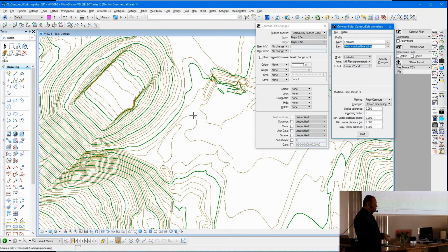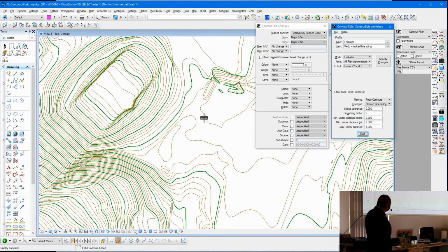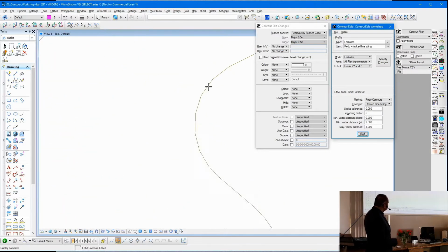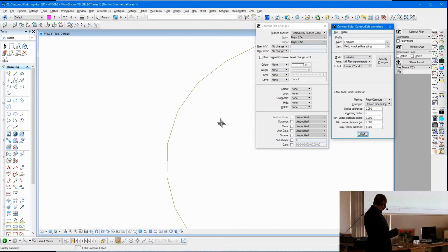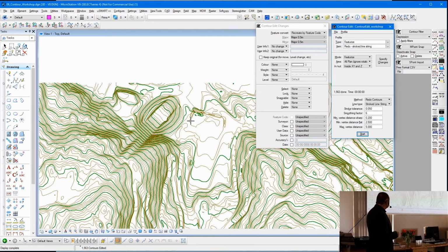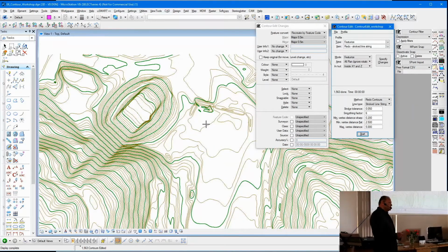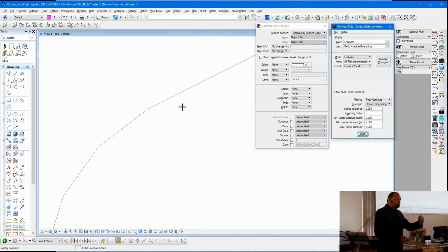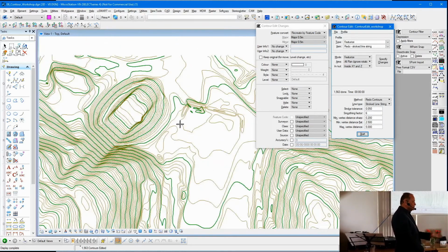And now we're going to refeaturize them as line strings at a particular tolerance, where we specify how much the line is allowed to deviate from the curve. Okay, and that's over here. Where's the tolerance? So we know that there won't be more than a 5 centimeter deviation from the contour. And we've got something that, zoomed out, looks like curves, but close up you'll see it's a polyline. And then your GIS system will probably be happy with it.